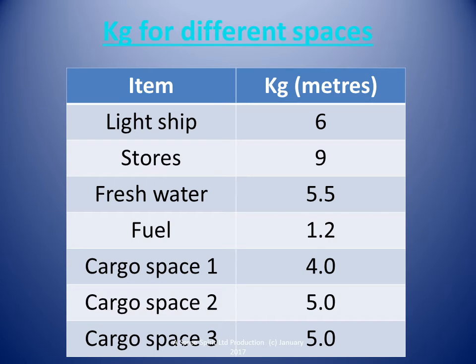Here is how we determine the vessel's KG by using moments about the keel. The KG of the lightship was determined by the inclining experiment or approved alternative. Every weight added to or taken from the vessel will affect the KG if every weight is placed in specific locations. Each item's center of gravity above the keel is known or can be found. For example, fuel in a double bottom tank. The height above the keel of the center of volume of the tank is known. The KG, even for a partially filled tank, can be determined from the dimensions and characteristics of the tank.